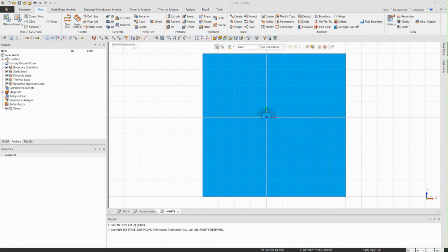Which type of settlement? Specifically, we need to assess the settlements along the tunnel lining, and there may be resultant displacements, or the vertical as well as horizontal settlements we can see. We can see the settlements at specific portions, especially the roof portion of the tunnels, and then we can assess whether those settlements are significant or not.